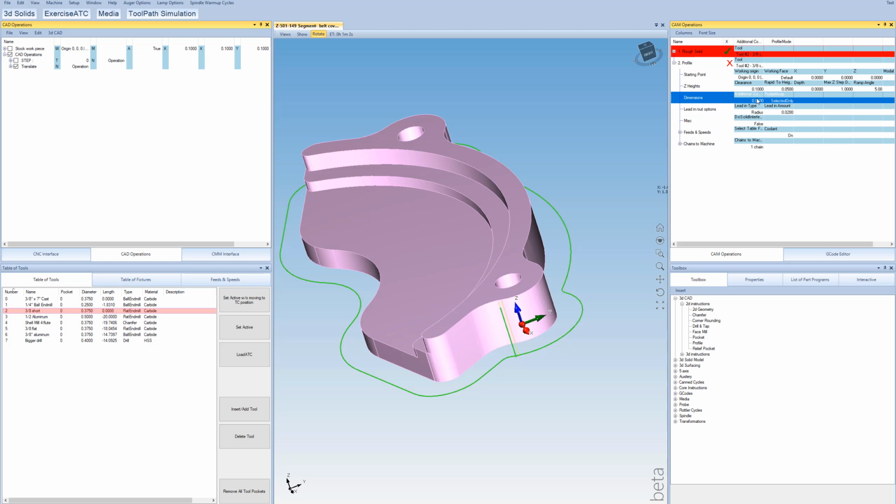And now we're going to basically just finish this flat area right here. So we'll do, oops, not a profile for this one. We want to do a pocket for this one. And then come over here and select on our chains 3D face. We'll just grab this face right here and refresh that toolpath. And so that looks good. So we probably could go ahead and cut this the way that it's decided to cut it. But what it's really doing here is just doing a pocket from this outside and all the way around the perimeter here. That's basically just this face.